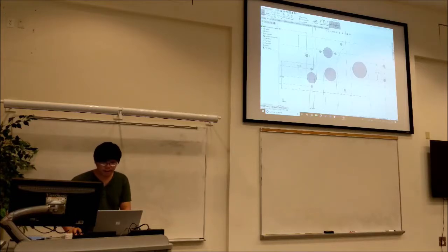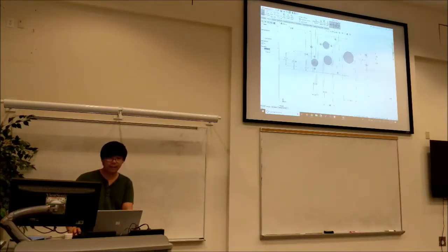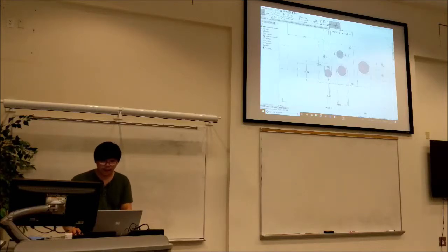And then for the standoff, just to place it, we can make it tangent to the edge of our gearbox, which will be here for the plate. So we can do that. And again, this is up to you. You don't really need to make a tangent. You just need a standoff somewhere in your gearbox. And then we're going to make this equal to this, because it's the same 3/8 inch standoff, the same ID. And then from here to here, we do the same thing.